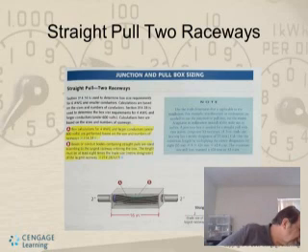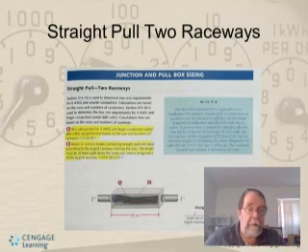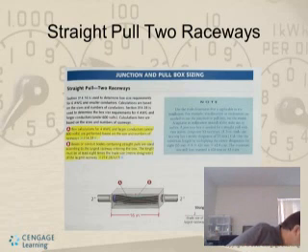So you take the diameter of the raceway and how many there are entering the box and leaving the box. Boxes or conduit bodies containing straight pulls are sized according to the largest raceway entering the box. The length must be at least 8 times the trade size. Okay, when they talk about that, it's the metric designator of the largest raceway. A box width. Now there is a note here. Use the trade dimensions that are applicable to the installation. For example, if millimeters or centimeters are needed to size the junction or pull box, use the metric designator in millimeters instead of the trade size in inches.